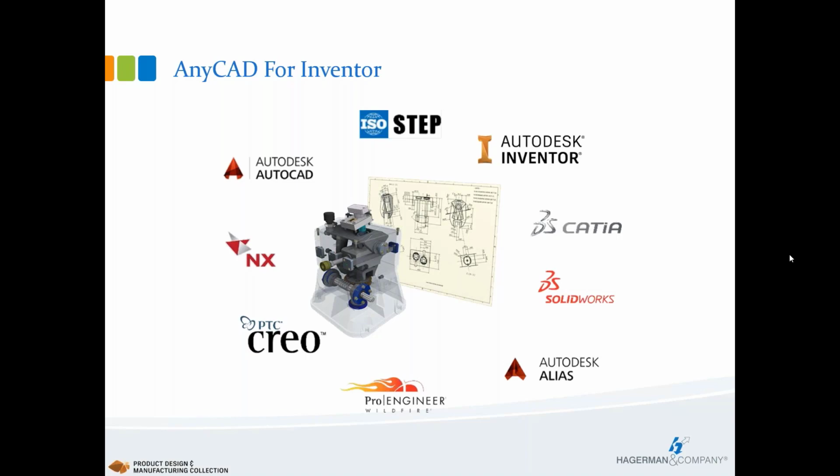So take SolidWorks, for instance. If you are working with a SolidWorks file and you placed it into an Inventor assembly, and the SolidWorks users saved the changes there in the shared folder that we've placed from, the updates automatically show in Inventor. The update icon becomes available inside the software. You just click update. It updates the files that changed. There's no retranslation needed. We don't have to delete the file, bring it back in, reconstrain it. All the updates happen there live.